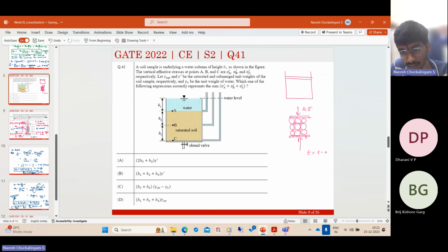But as we allow drainage, under the pressure, the pore water will start flowing. Why? Because of Darcy's law. When we apply this delta sigma, the pore water is pressurized, so the pressure head increases, and therefore the total head increases. And away from the point of loading, the pressure head is the same, right? So water will flow from the pressurized regions to the unpressurized regions. So basically you're squeezing water out of the soil under an applied stress.